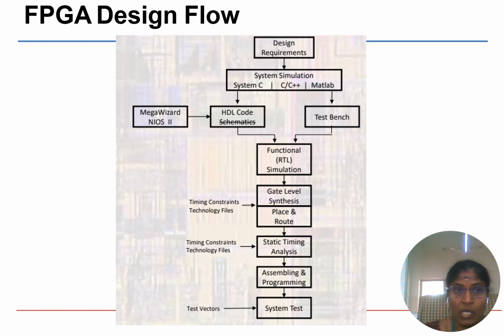Once the components are placed, the interconnections are established. That is nothing but routing. Once the placement and routing is obtained, we are going to check the timing analysis. Timing analysis is nothing but if the input is given, when the output will be generated, what will be the delay between input and output. Everything is going to be tested by using static timing analysis.